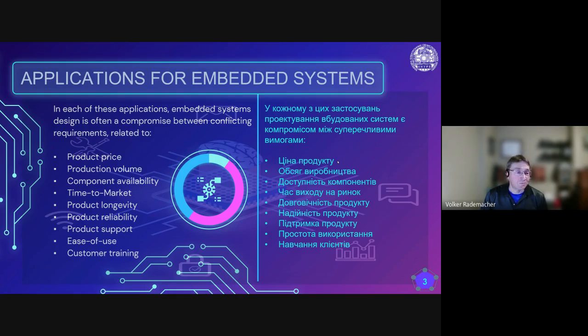The company was trying to avoid hooking up all the comparators to the microprocessor, and was just attaching an A to D converter to the ground fault measurement to measure the severity of the ground fault. The circuit worked perfectly.